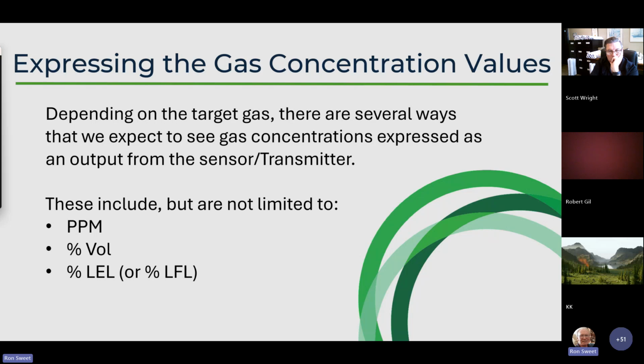To monitor hydrogen in particular, because there is a sensor for monitoring toxicity level hydrogen at 0 to 2000 ppm, to monitor for its combustible capabilities, you have to make sure that you are specifying or asking for a combustible concentration hydrogen sensing type element if you're monitoring for hydrogen in an area where you're charging lead acid batteries, because that goes up, like I said, to 40,000 ppm, and 10% of that, where we would typically bring on the ventilation, is 4,000 ppm.